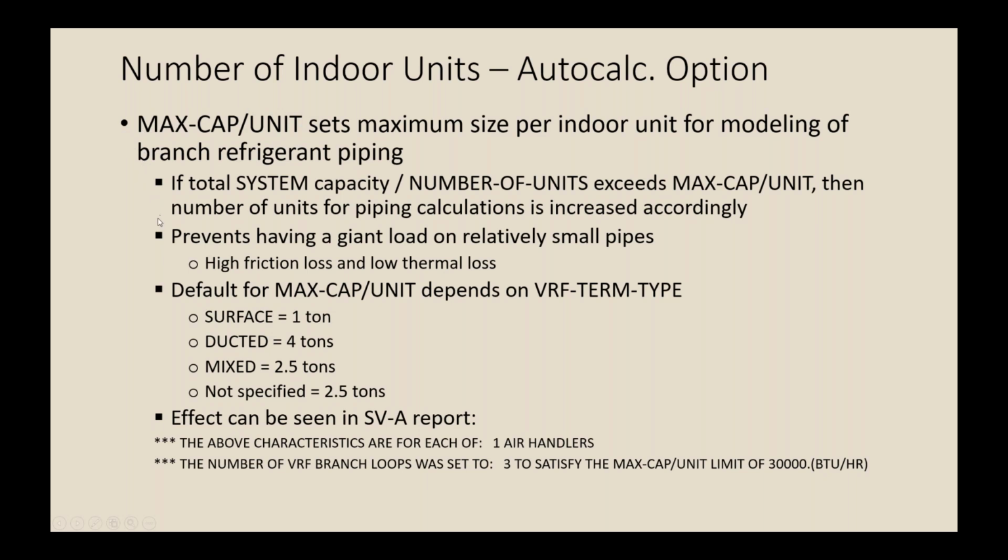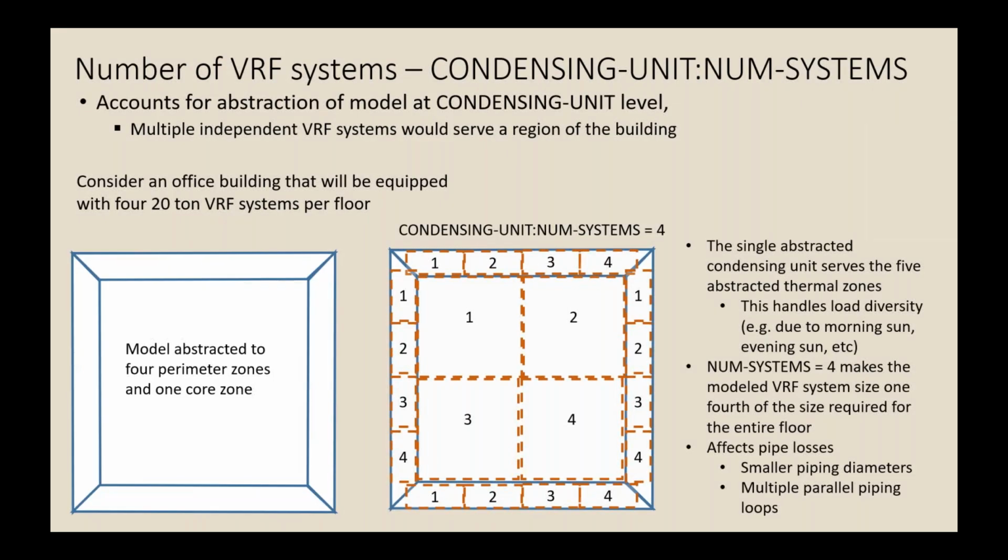So that's a bug in the program right now in eQuest. It will function if you enter it manually in the INP file. There's also a workaround that Bill Bishop has posted on the eQuest user list, and I'll try to post a file following Bill's instructions to my website for people who want to access that through eQuest.